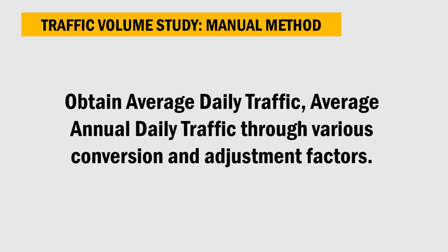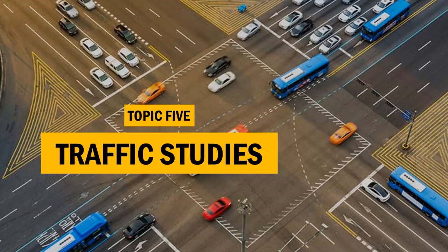The data obtained from traffic volume study can be used to obtain average daily traffic, or ADT, and average annual daily traffic, or AADT, through various conversion and adjustment factors. In this video, we discussed traffic studies and how different traffic studies are conducted.